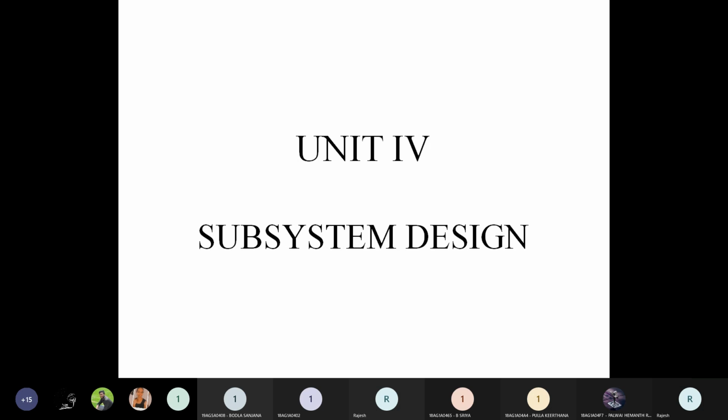So what is hierarchy? They build in a top-down design approach. What is your top module? What are the sub-modules? Like that, they go on building the modules and combine them together to complete your IC. So for every IC, the logic designer analyzes the logic, those logic are implemented using components by the circuit designer, and the layout designer creates the layout of that.